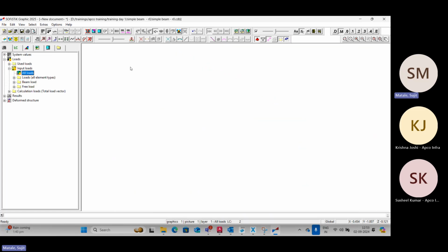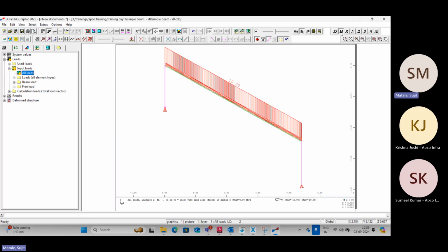See graphics. I'll just give you a brief of this graphics. Graphics has got a tree menu on the left hand side. On top of it, this is one thing. There is a pin and downward arrow, which has got 4 trees basically. System values. System values stands for the structural line numbers you modeled, group numbers, cross sections, all the modeling information will come in system values.